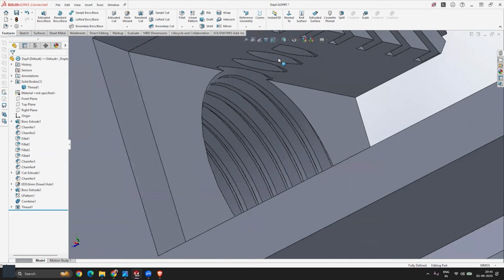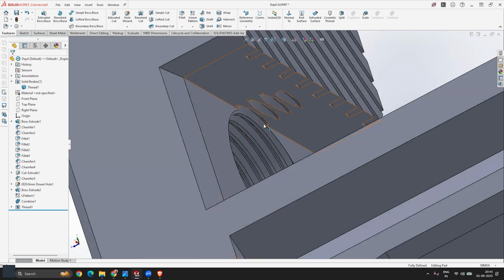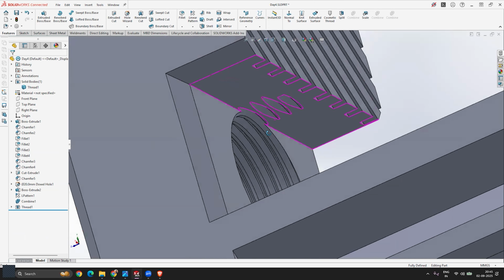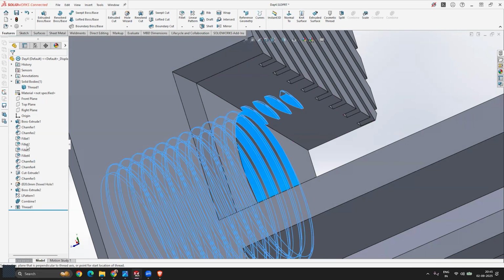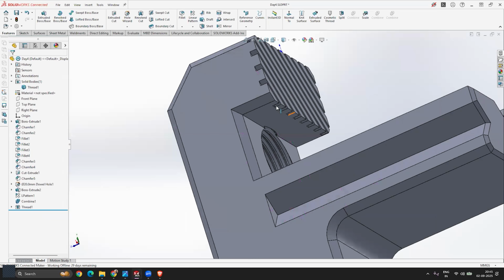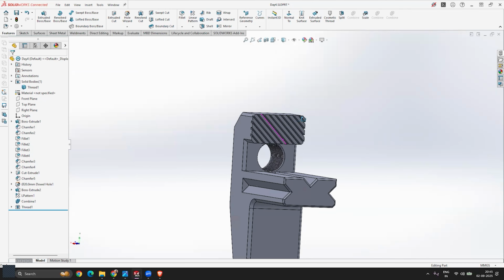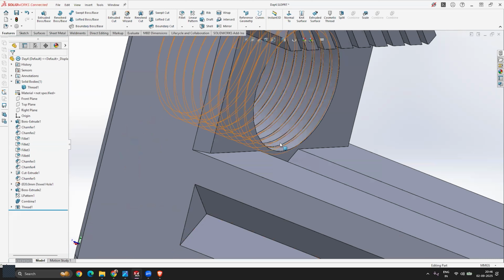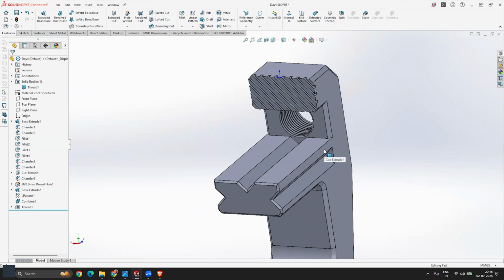And since the hole was almost touching, because we have extruded this thread a little bit extra from the body width, we can control that using the thread length that we have considered. So instead of 25, let's make it 20 only, right? 20 only. And now click on finish, and it will not extrude more than that. Here you can see like this, right? So this is how you can create threads inside your body in SolidWorks, right? It's a very simple tool, but standardized according to the thread tools available in the market, right?